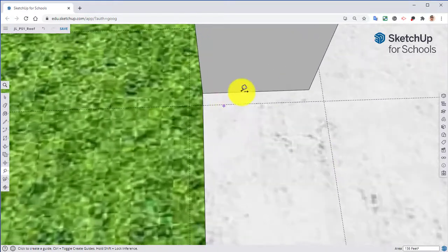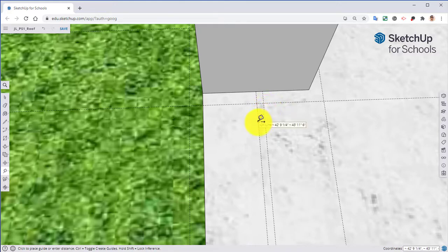And for the door, we need to find the center point of our door frame. So right here. So we have 2 inches right here. Our front door is going to be 1 3/4 inch. So we're going to go 0.25 in this direction and 0.5 in this direction. So that we have that right there for the door, and we're going to create our door at 1.5 inches.